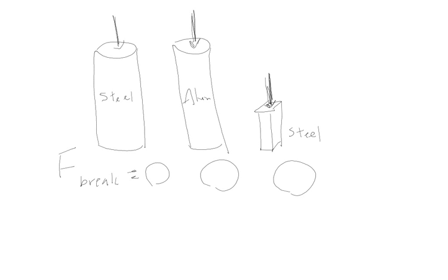How about the force required to break the two steel columns? Why is the force required to break the first steel column much greater than the force required to break this second steel column? Well, it's obvious. The first one is much larger than the second one. So something that's larger and made of the same material is obviously going to be stronger. So this is a bad comparison. If I try to use force to compare these three things, values are going to be all over the place. I really can't make much of a comparison. In fact, can I say that the steel used in the first column is stronger than the steel used in the third column? No, they're the exact same material.